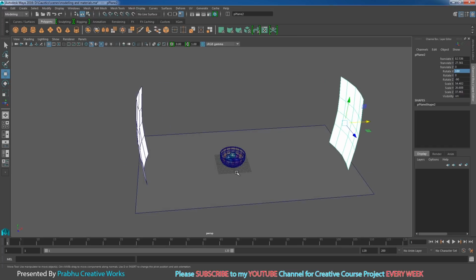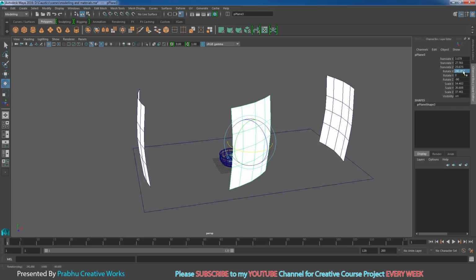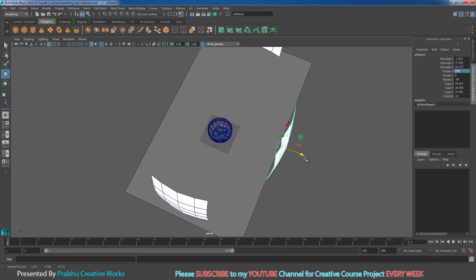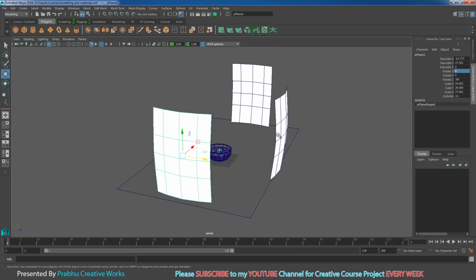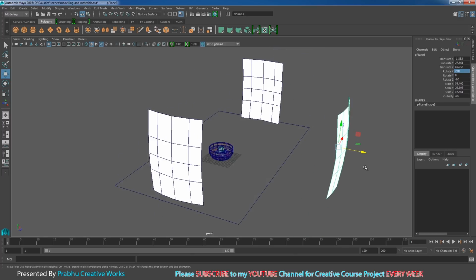Now I want one in the front side also. So press Ctrl D and I want to move this one in here. So I want to rotate. This one is 240 or 270. So you want to rotate X in 270. I will place it exactly in front of our crystal cup. So now we place our reflection source for our caustic object. I will move the front side reflective material further.